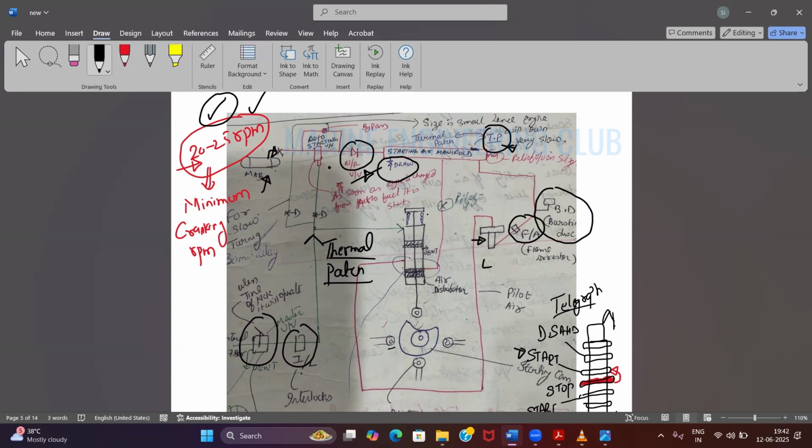Flame trap and flame arrestor are the same thing, yes. Another name of arrestor is trap. Okay, I will come to one by one on all these points. I will come to interlocks also. I will come to flame arrestor also, and bursting disc. Now, in case of Sulzer engines, we don't have a bursting disc, but in place of bursting disc, they have given a relief valve on the manifold itself. Is it clear? Yes, sir. Okay. All right.